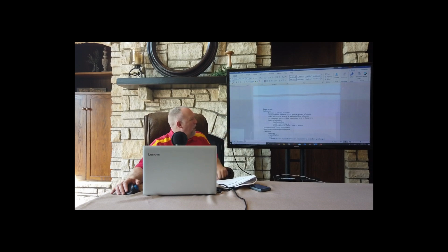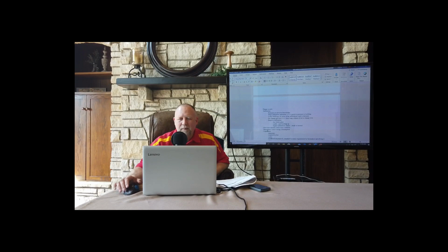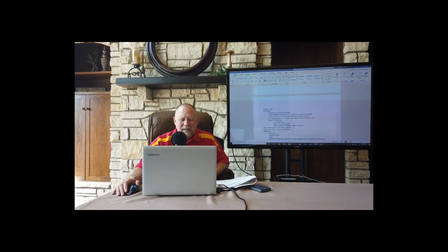Infiltration. Okay. If you're wanting to save energy, I'm going to suggest get better glass and seal up the building. In other words, caulk. If an owner is looking to me and saying, hey, I want to save energy, where should I spend my money? The best bet is not, let's just add some insulation to the roof or the walls. Your best bet is to cut down on your infiltration and buy better glass.